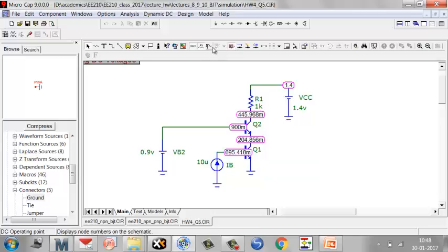But let's see here. All right. You see this point here, on. It tells you whether the transistor is on or not. And it also tells you whether the transistor is in saturation or active. This particular simulator, for active mode, calls it linear. Okay. So let's see on. It says both are in saturation. Both are in saturation. So when we designed it, we took what? 0.2. Right? We took 0.2 and we just saw from the transistor that 0.2 was not really accurate.